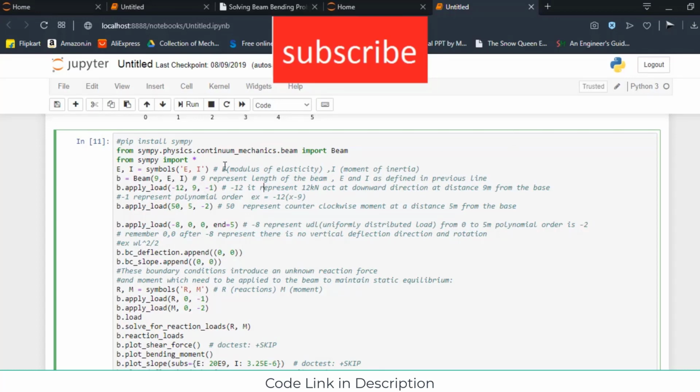So minus represents that it is acting in a downward direction, 9 represents the distance, so it acts 9 meters from the base, okay, and minus 1 represents the polynomial degree. For example, if you simply write a polynomial, then its equation is minus 12x minus 9. If you know about the bending moment diagram, then you know how this minus 12x minus 9 comes. Now I am going to apply the second load.